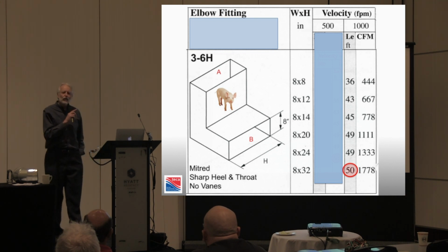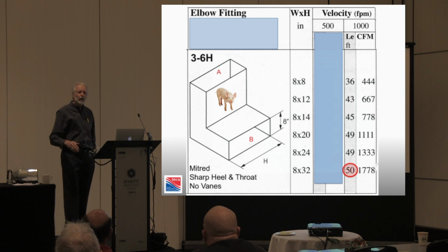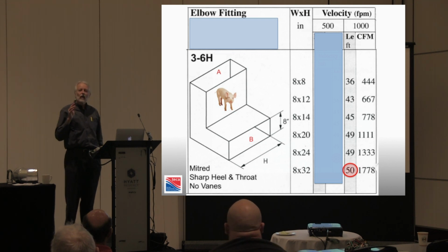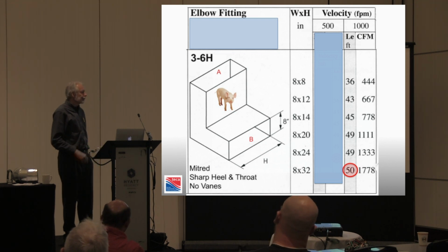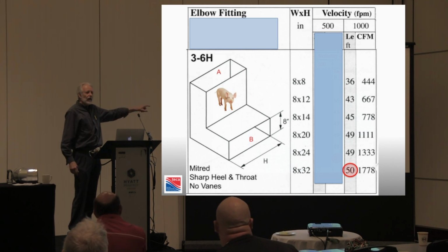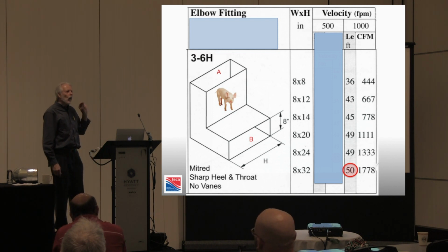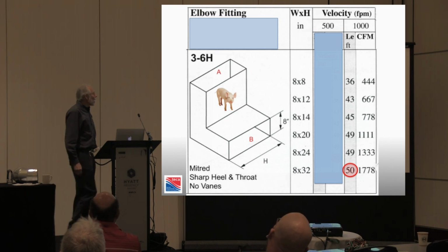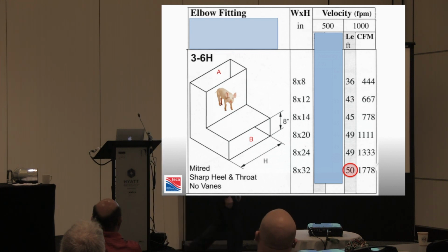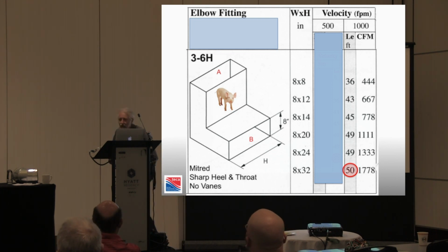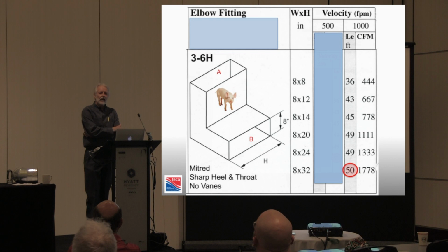One thing that I want to focus your mind on totally today, because this is a screw up that I've seen for 37 years all over BC. This single fitting, which I've labeled as a pig because there are worse, changes the air 90-degree turn. The net result is that this air making this 90-degree turn thinks it's gone 50 feet of straight duct in that one single turn. That's the same as moving the furnace 50 feet away from what would be its ideal central location, and that's what that single fitting does.